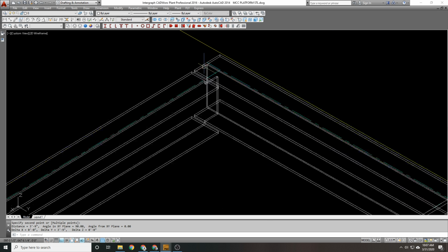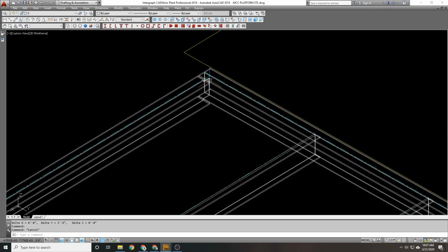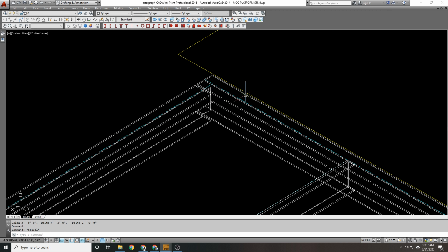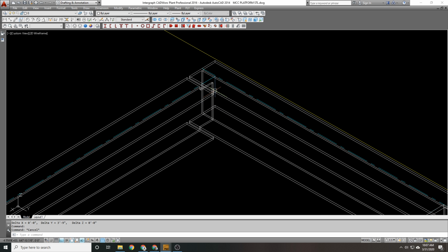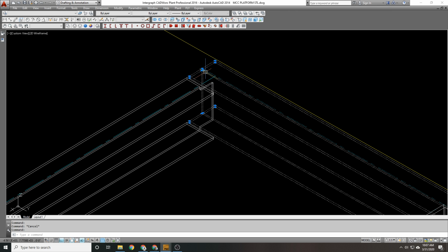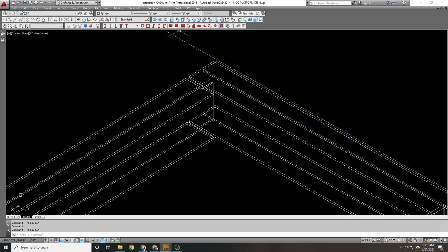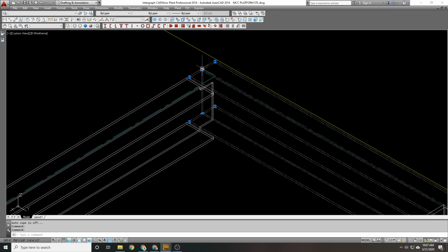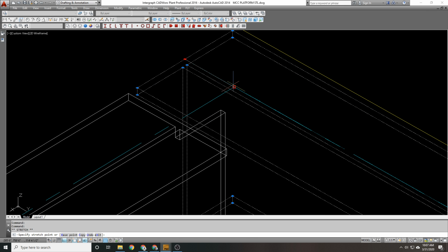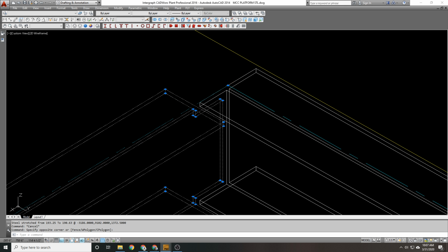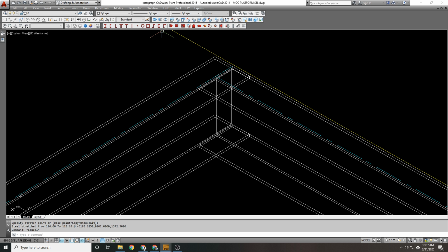So I've already got these coped out. These are my through members. I want to do that because that building is right here, and I want whoever's installing this to be able to access the bolts. If this goes the other way, let's turn my auto cope off so that I can bring this back to here and bring this one over to here. Let's say it's this way.